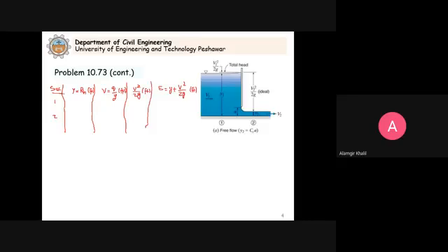Now for section 1, we can calculate the values here. The depth is 1.6. We start from 1.6, which is produced by the gate. Clear? This will also be equal to the hydraulic radius. So the depth, this is Y, is 1.6 at the first section. The velocity you can calculate as discharge by the depth. The discharge is given, so this will come out to be 40.625.